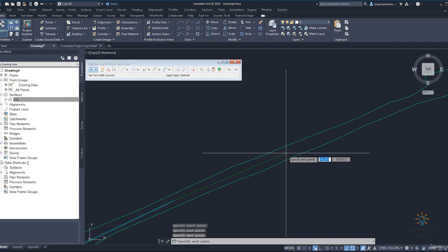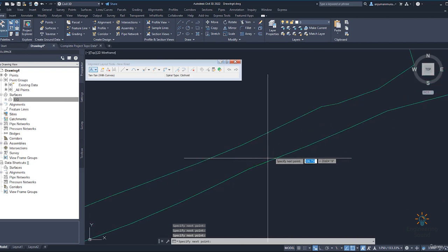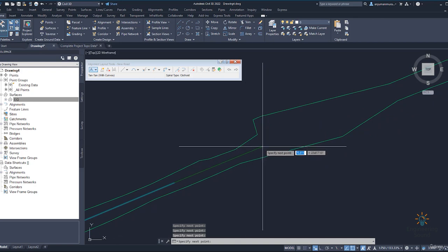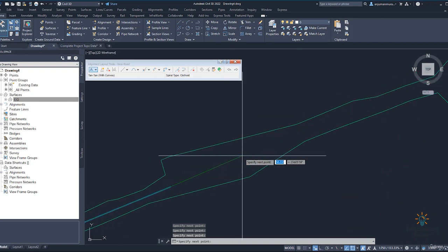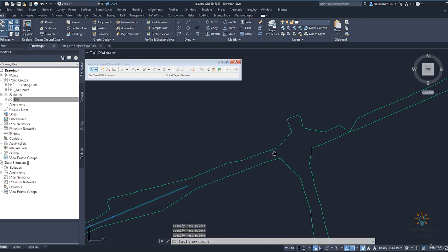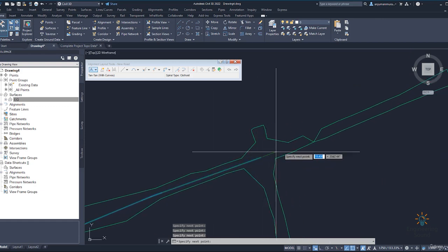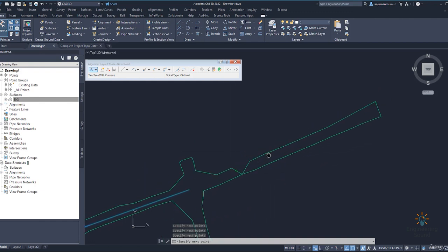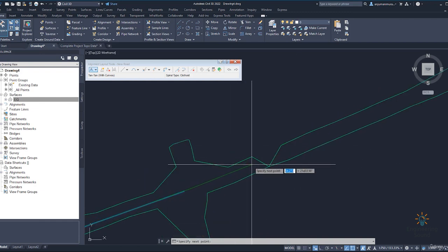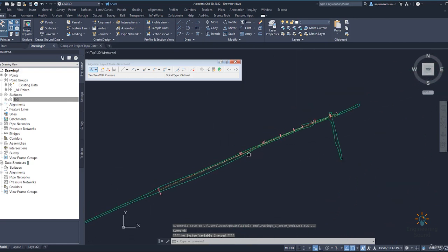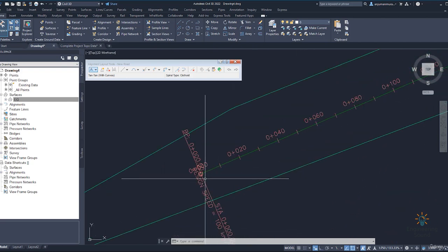like this. You can just create it, but make sure when you are going to draw the alignment, your points and topographical map should be on. Then you can know that I am not crossing the limits, I am in the limit area. If you go and select, there will be a lot of demolish options, so you can just select it from here up to here. Just click here and press enter. Once you click here and press enter, you can see that your alignment is drawn successfully. So here it started from here.